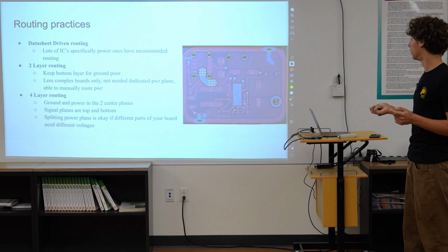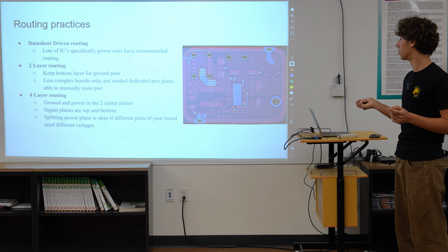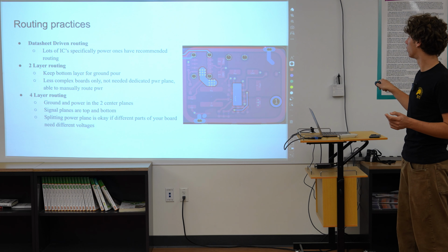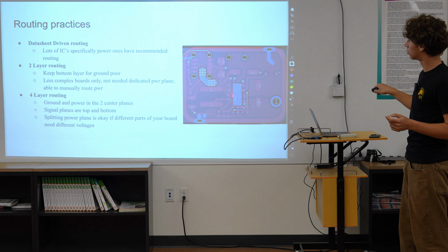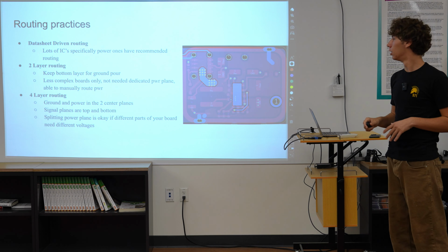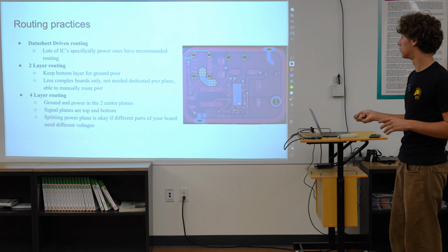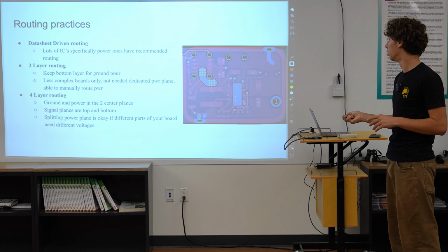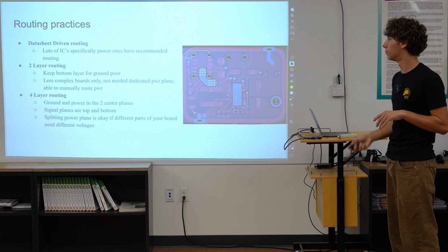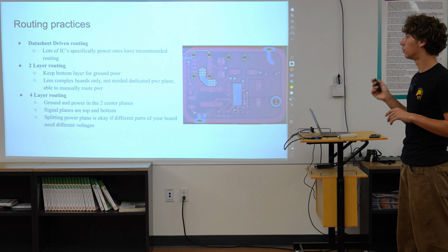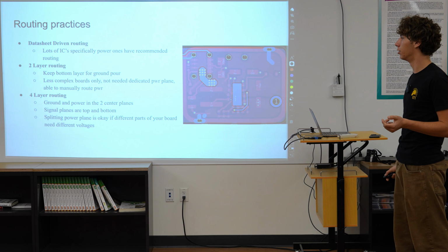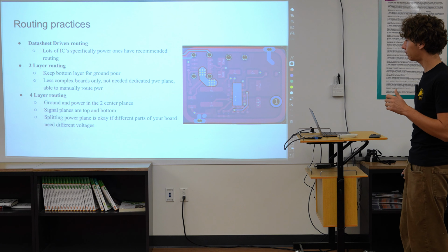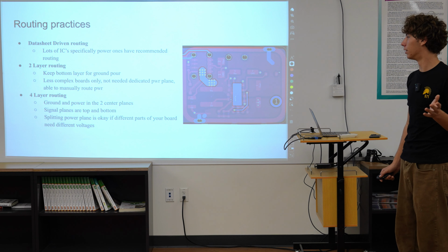From any of these pins, they have a clear shot to any of the other pins. For example, if that ground needs to pull from that ground, it can just go right there. So we definitely don't want any trace that goes straight down the middle. But for small rectangles like this for heat dissipation on the switch node, or a small trace like this, it shouldn't really be a problem. For less complex boards, that's what I would recommend. For more complex boards, you're probably going to want to do four-layer routing, and again, we'll get into that more later on.